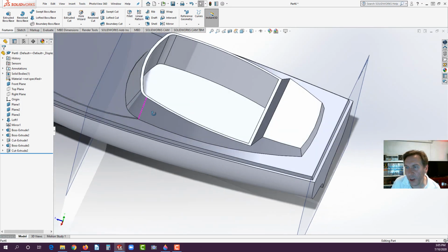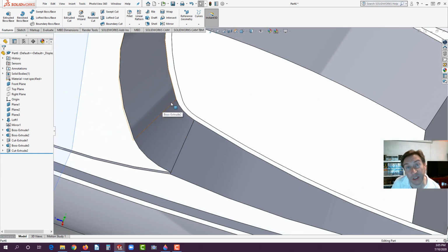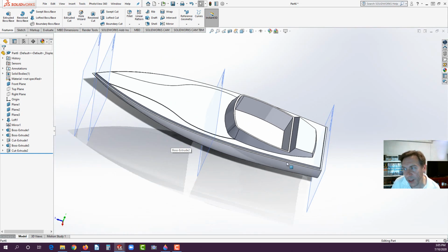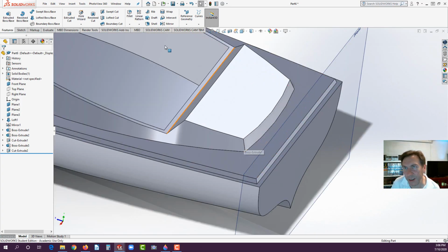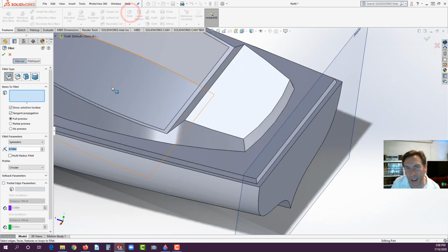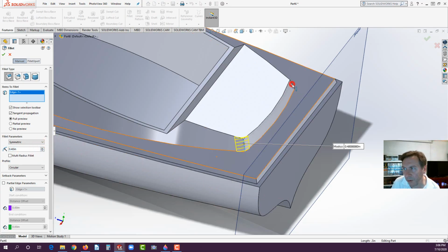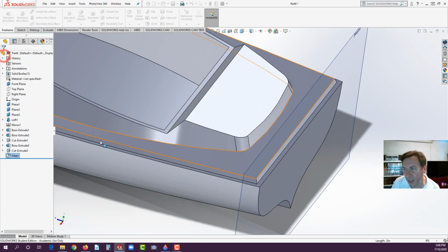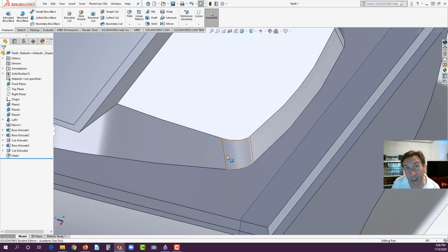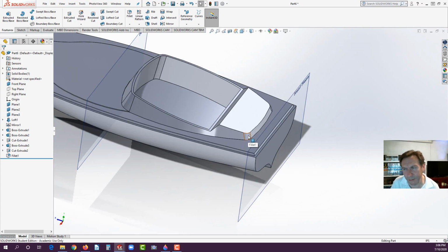And now we saw what happened here with that fillet and how it gets smaller. It tapers with the draft. Watch what happens when I put a fillet around here later on. When you add a fillet after the fact, it comes out very different. It's constant. And in this case, it blew out the preview. So I can only go with about 0.4 on this edge. But now look at that. It's just straight. There's no taper. I mean, there's draft on it, but it's consistent versus this one is actually getting smaller as it goes higher.